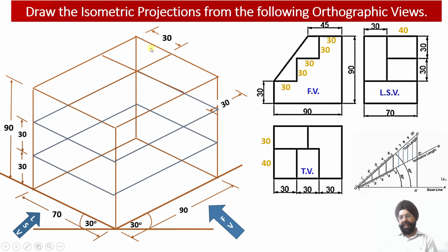Now this web which is turning towards the left side over here, but it is not reaching this last point over here. As this web turns towards the left side, we see from the top view, this information is available to us, that after a length of 45 millimeters, please check, the length of the straight portion happens to be 45 millimeter.